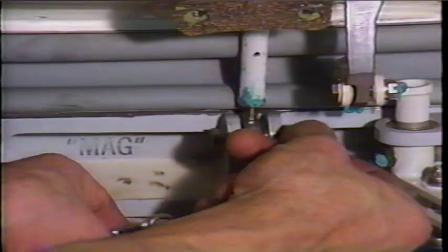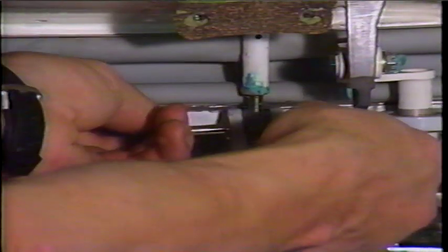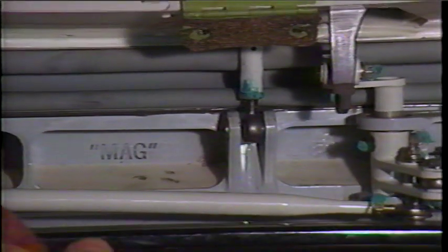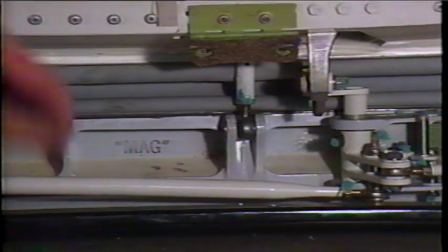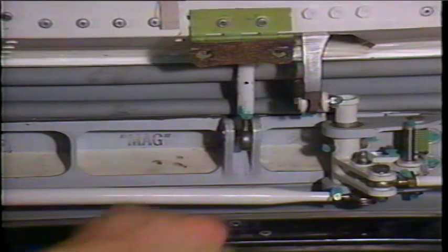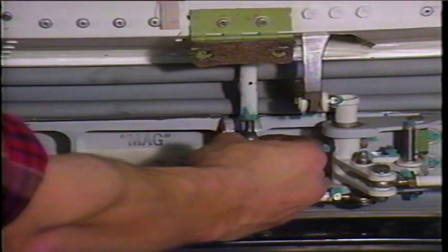To ensure latching without any gate preload, disconnect the upper and lower gate push rods from gate cranks by removing the bolt, washer, bushing, and nut. A note of caution: the disconnected push rods could damage the door structure while the door is being closed. Manually guide the disconnected push rods to prevent damage.